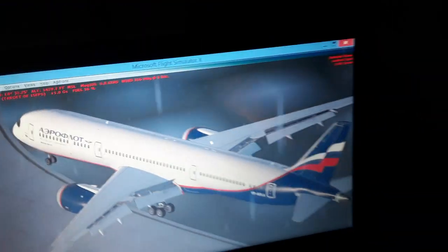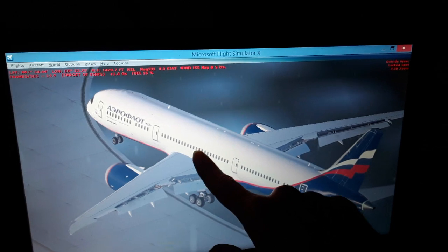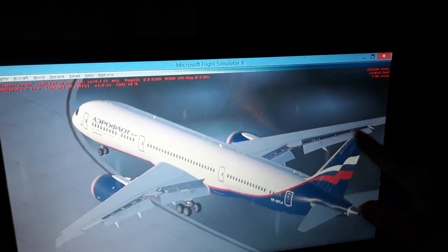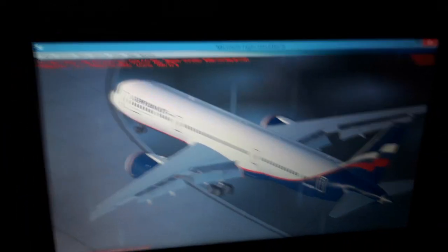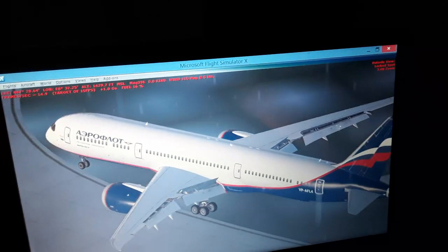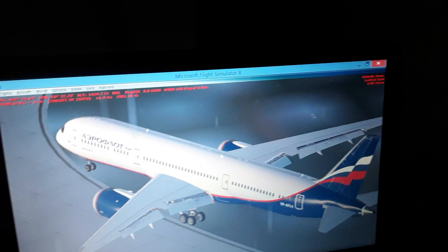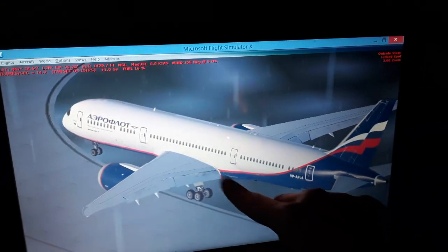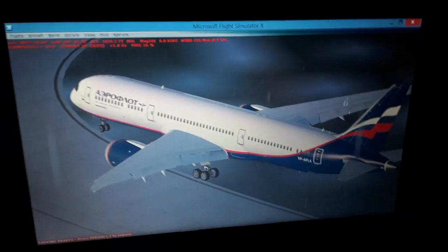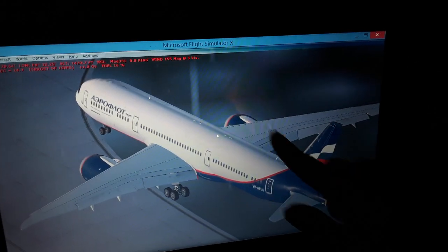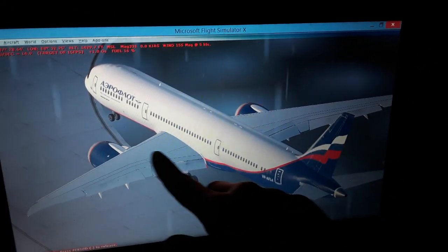So you can see we have the mean aerodynamic chord, 23% of the MAC, where the maximum aerodynamic lift occurs in the forward wings. It's also the position where the center of pressure is moving back and forth in the top surface of the wings. When we fly the stall, also the airflow becomes detached from the top surface of the wings, and the wings stall over here.